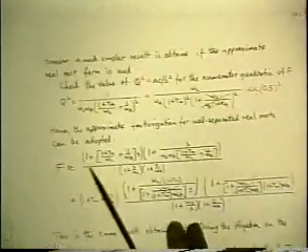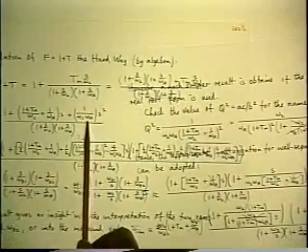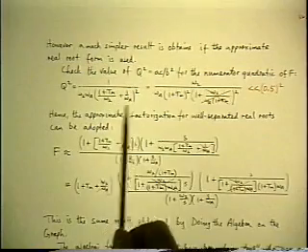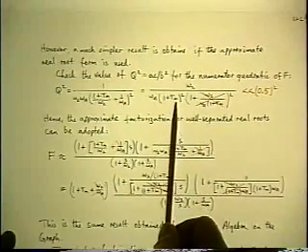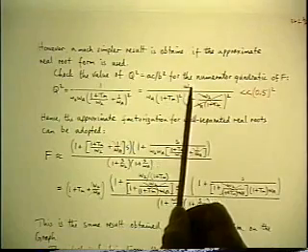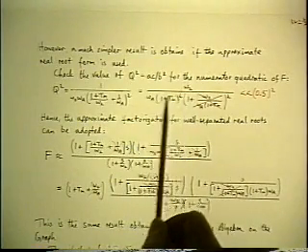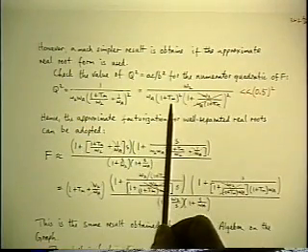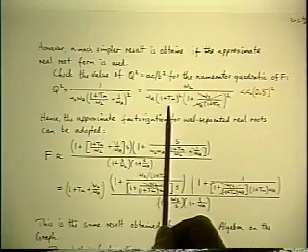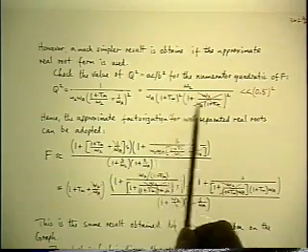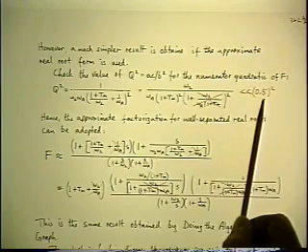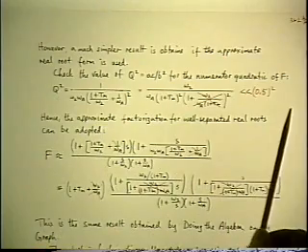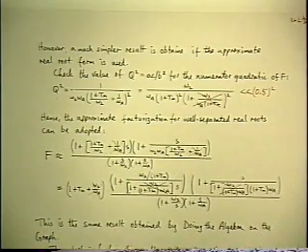which is the coefficient of the middle term. And in terms of the A1, A2 coefficients that we've had before, the q is found in terms of those two coefficients, and this is what it is. And it's easy to see right away that it's a very small number, because it's the omega 2, which is 30 hertz, divided by omega A, which is 2 kilohertz, and then divided again by the square of the midband value of the F, which is 11. So the resulting number comes out to something very much smaller than 0.5 squared. So this validates the real root approximation extremely well.